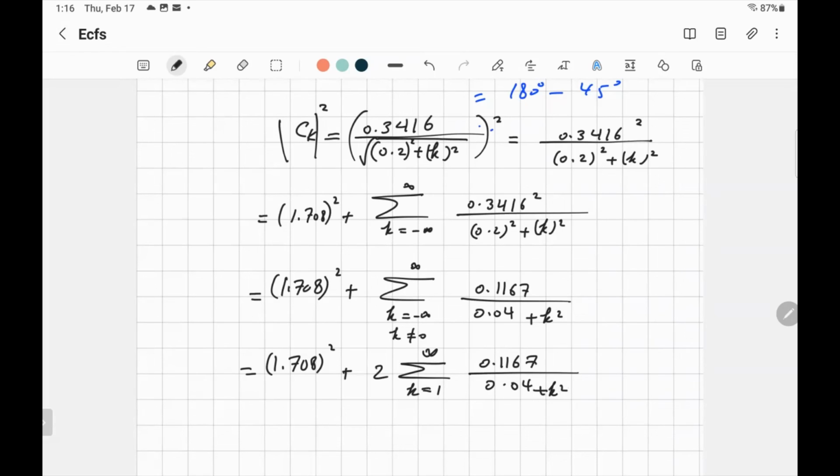Instead of calculating for positive k and negative k, I just proved that they are equal, so just get the positive and multiply by 2. And having the 0 out is another advantage, because if you have 0 inside and double it, it's not going to be right; it means you double the middle. That's why I like to separate. Then this sum can be calculated by a program for 10 terms, 15 terms, whatever, and you get the power of the signal.